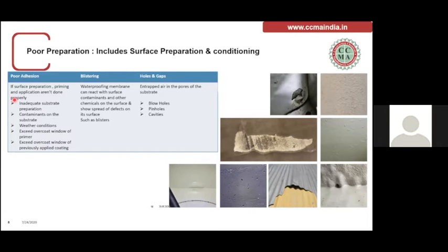Now blistering is something that is also seen in waterproofing systems, and it is generally because the chemicals in the subsurface can react with the waterproofing membrane which is applied over it, and that can lead to blisters. Also, the concrete is breathing, or some sort of moisture is available in the concrete, so that moisture potentially wants to rise, and that also creates the blistering problem.